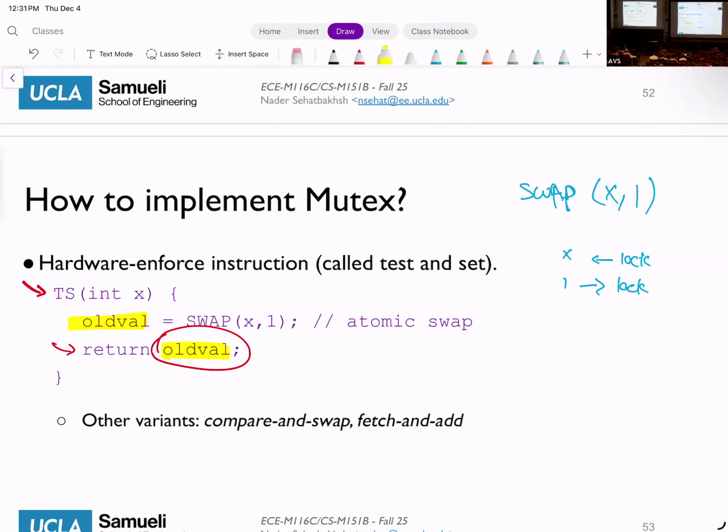The question is about how do we actually implement the atomic? There are 2 ways to implement an atomic. There is a transaction-based atomic. So there is this notion of transactional memories that allows you to do one thing at a time, so read and write at the same time. Or there is this kind of a failure. I'm going to actually show you how we implement it in RISC-V, and you'll see that both of them are options. So atomically, yes. You read, but if someone else writes to it, you fail and you redo. So that's a possibility.